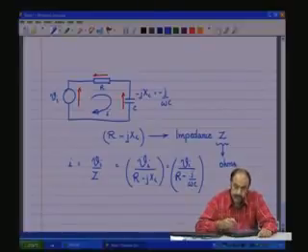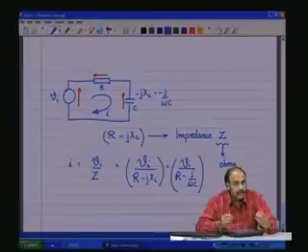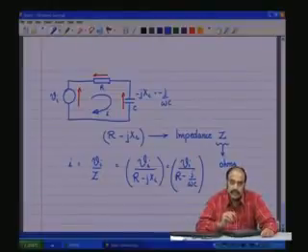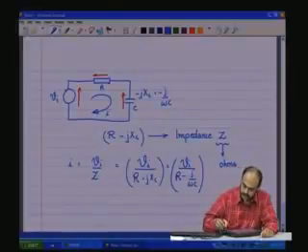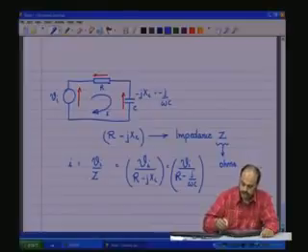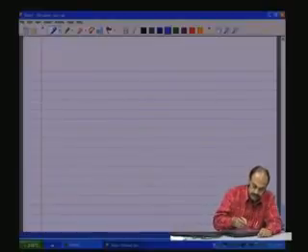Okay. So, this is the steady state value. One should note that the state equation is the most general, and this is a special case. Let us look at the state equation of this particular circuit and then see if you substitute the j omega for the d by dt's, you get back the steady state equations.